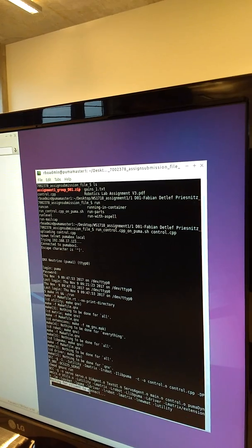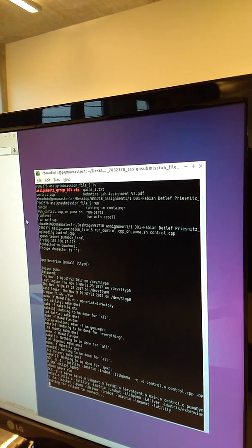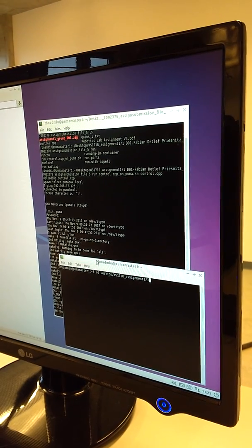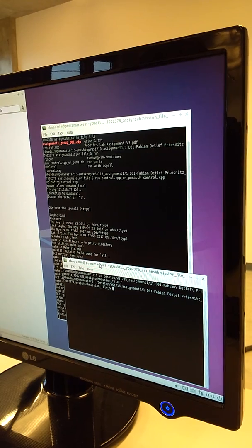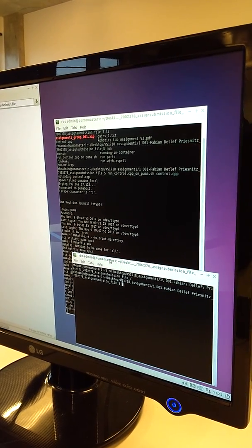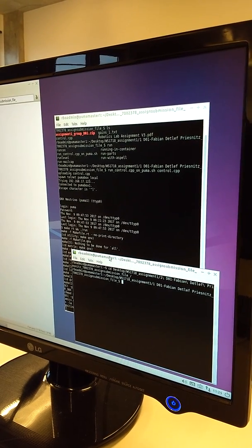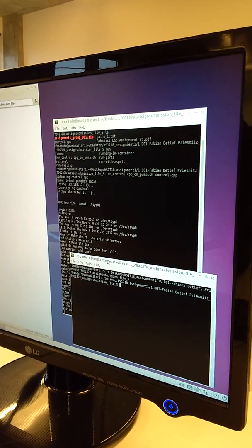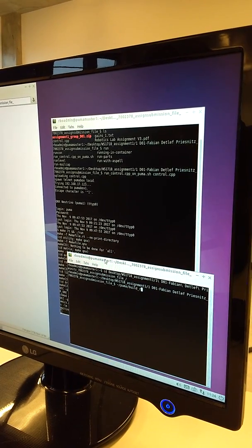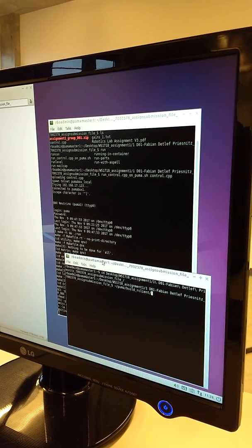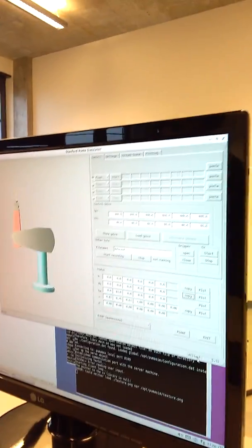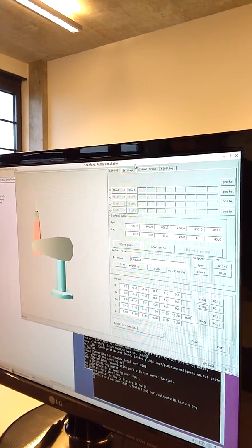So at the end of this, it says waiting for RC client to connect, and then we need a second terminal, where again we go to the solution files here, and from this one you now want to start the PUMA simulator locally on this machine. And you need to make sure that you start the simulator that's compiled as the remote client. So here on this machine there is already a pre-compiled version in the PUMA repository. There's a build folder called build RC client, and there we have a PUMA sim. And if we start that PUMA sim, you'll see in the bottom right corner here it says RC client, which means it's not running the simulation locally, but it actually connects to the QNX box.